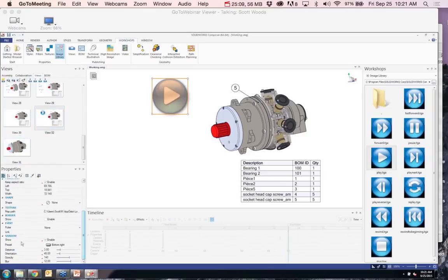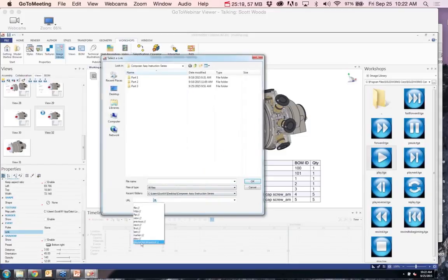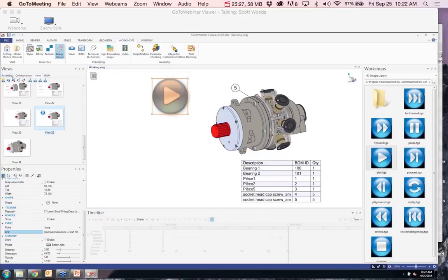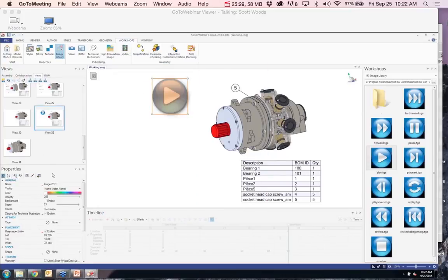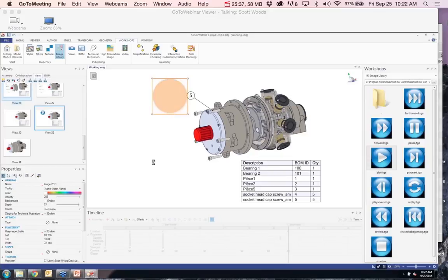And I'm going to go ahead and add what's called an event link. So in the properties of that button, I have a link. And in this link, I just want to reference the animation sequence of what I just made. So play marker sequence. And I want to find the one I just made, which is the start rotate. And just say OK. And really, it's as easy as that. Now when I export this out as an exe or view it in the player, whoever's going through this document will have the ability to go